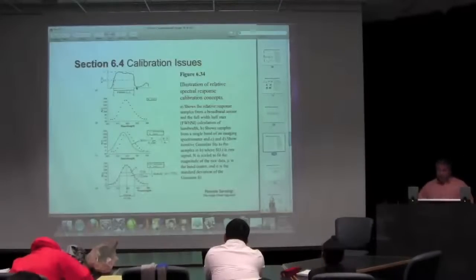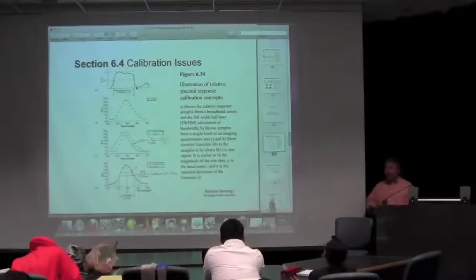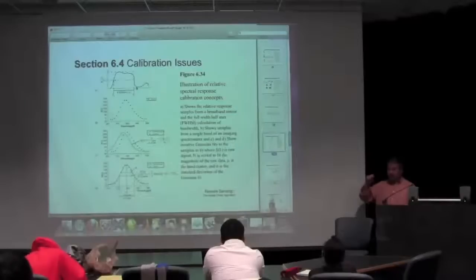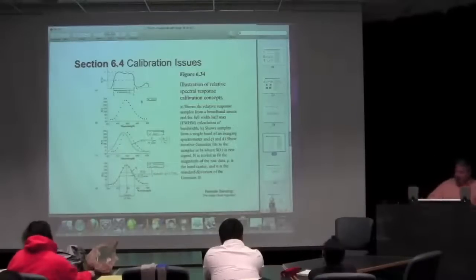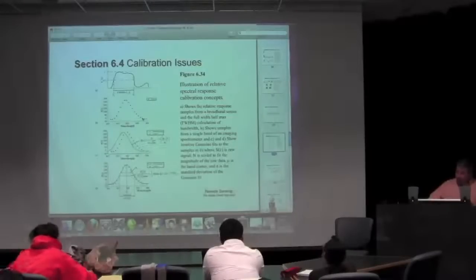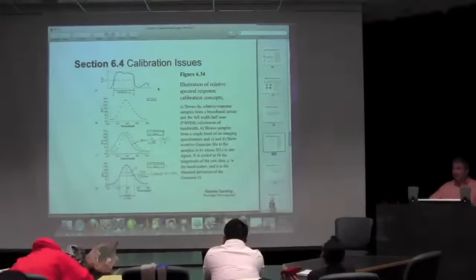Right? So that you can go ahead and measure on a monochromator. You can take your detector into the lab, place it in front of a monochromator, expose that detector to different wavelengths of light by allowing the monochromator to move through its full range, and record the signal that comes out. Now, one of the problems is once you start getting hundreds and thousands of detectors in a hyperspectral system, that becomes, well, a big data management problem more than anything else, to keep all those relevant spectral response functions around.